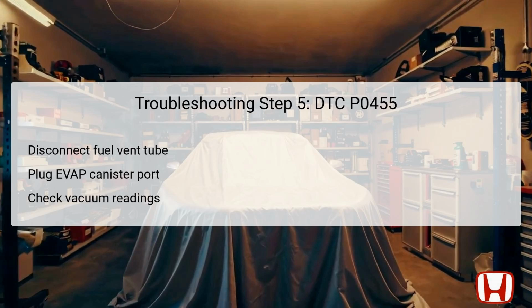The vehicle is then turned back to the on position, and you must apply a vacuum to the line until an FTP reading of approximately 1.90 volts is reached. Monitoring the voltage increase is crucial. It should exceed 0.2 volts under these conditions. This step serves to isolate potential leaks through other parts of the EVAP system.